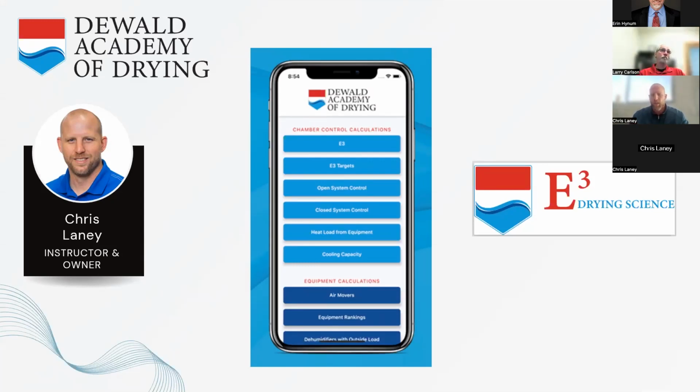So to give you kind of an easy summary of what that means, if I'm drying Larry's house, and Larry's house has an E3 number of 100, and you're drying my house and I have an E3 number of 200, what that means is my house is going to dry twice as fast as Larry's if all else stays the same. So that's really what E3 is.